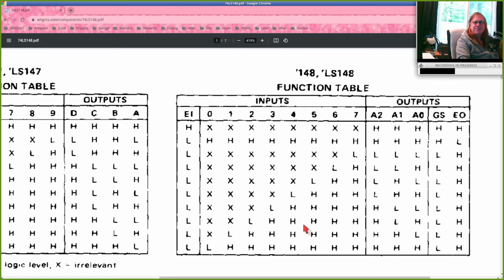And then when the CPU knows that some event just occurred, it can look at these 3 values and know what the highest priority event is. So if at the same time power is failing, the user clicked a mouse, and the clock just ticked, it would look at the output of this chip and it would see 0, 0, 0 and say, oh, that's priority 7, we've got a power failure. And it could go off and process that. Does that make sense?